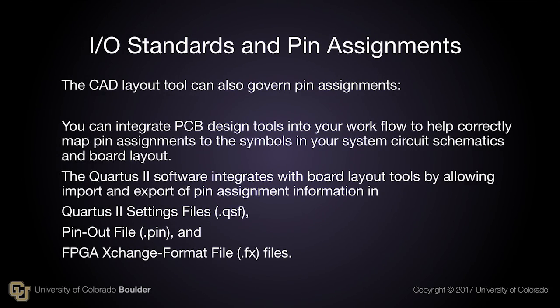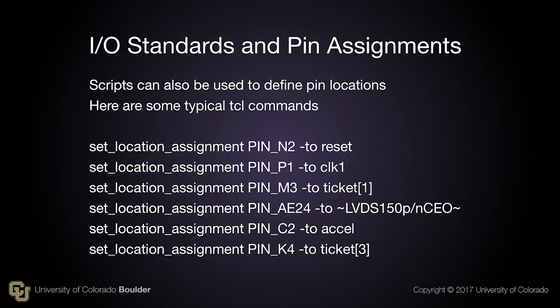Integrating the PCB layout CAD tool with the FPGA design flow can help reduce pin assignment errors, as design rule checks can help assure the circuit board and the FPGA assignments match. Many FPGA designers like to automate the pin assignment process with Tcl scripts as shown here.